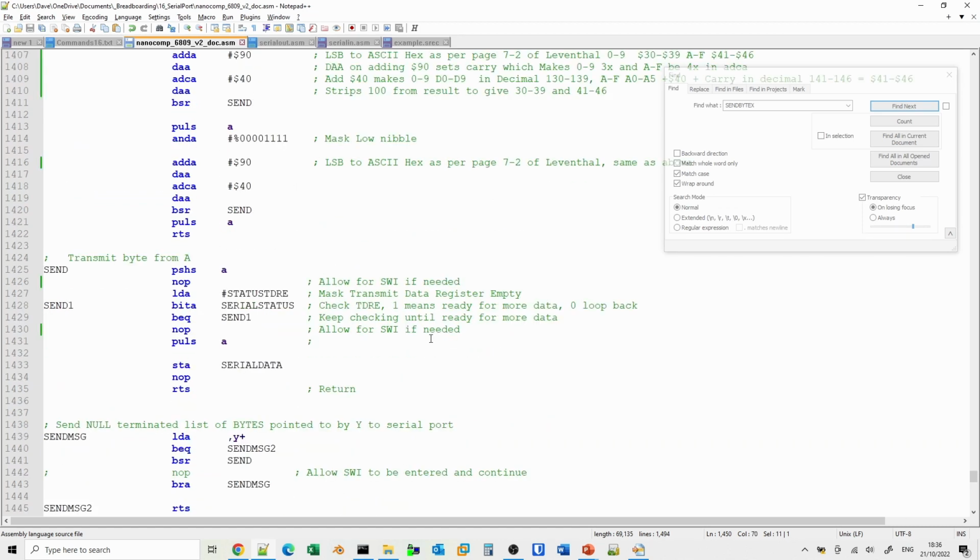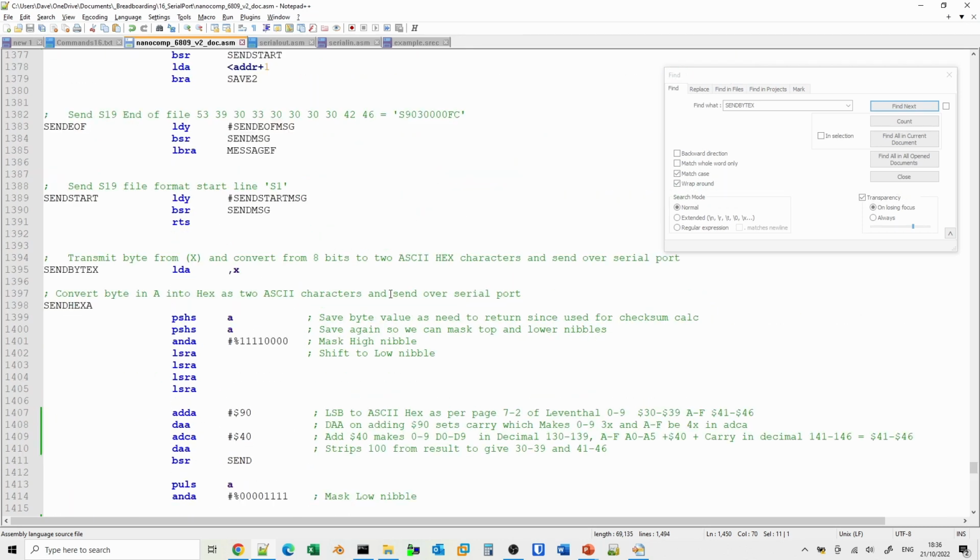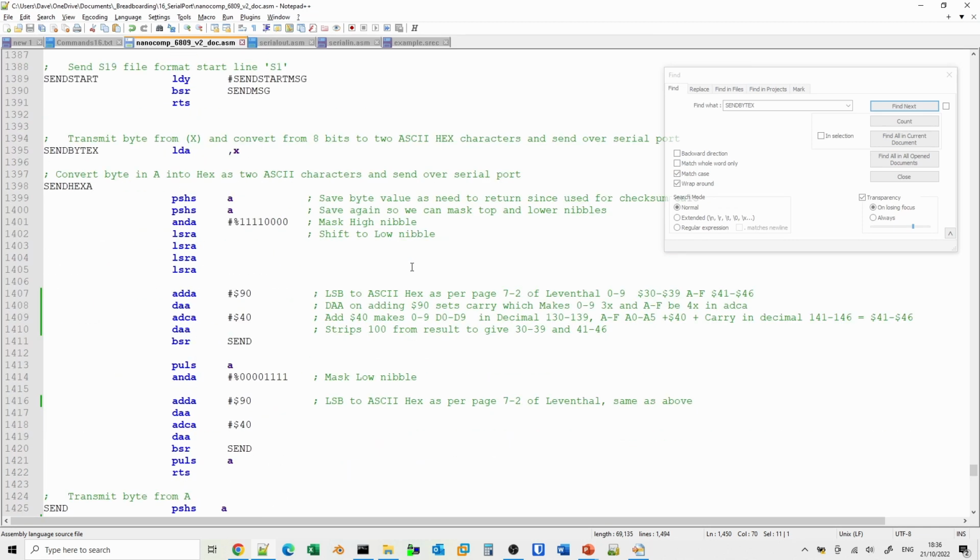So it's quite complicated, the code within the send and the load, but it was similar to the code that already existed. The only bits that needed to be changed in a major way is some of the checksum calculations and the fact that the original code would send 1s and 0s as 2 different frequencies by toggling a bit on the parallel interface adapter, whereas what we've just been able to do here is take the full value and send it to the serial port, which makes it a bit simpler.